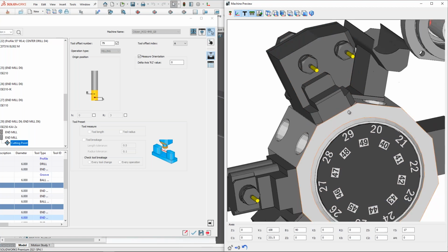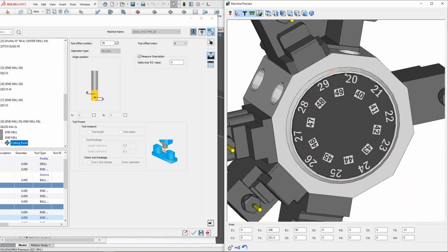Of course, you can calculate it differently: as there are 10 stations, 360, a full circle, divided by 10 is 36. And the index position is just divided by 2, and you will get 18 again. But be aware that not all turrets have it really in the middle. I've seen many that are not really in the middle, so pay attention to that as well.